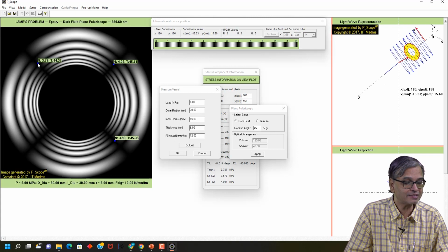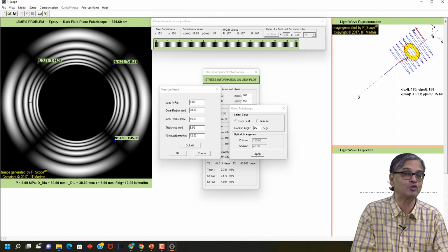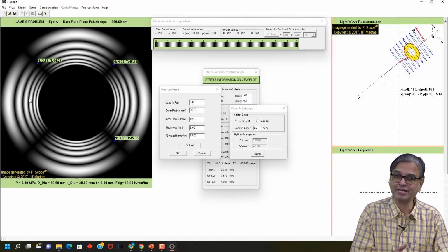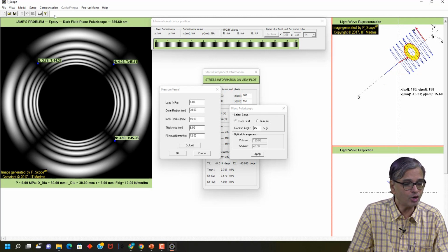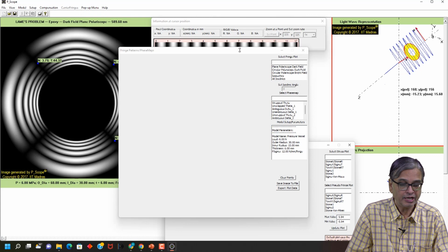And you have this labeled like this. So, you have the comfort when you want to learn photoelasticity, how to label the fringe order. For known problems, you try to experiment with this simulation package. So, you gain some understanding and extrapolate it for a practical problem. Okay. Now, what you have is, I have collated all this because it is theoretically done. You have all the isoclinics put.